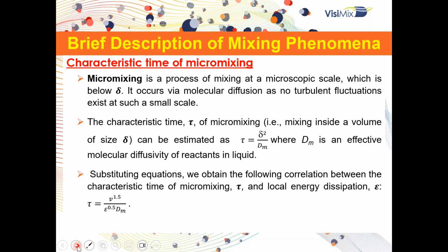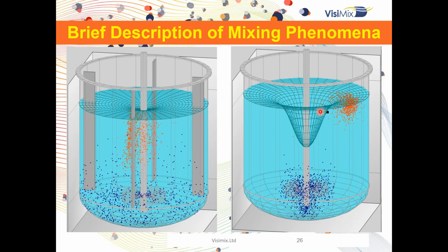I will not go deeply into it. It's very interesting to do. I include another 2 slides showing that we are able to take into consideration fluid elements in different kinds of configurations and understand why, at the same time, as you can see here, the fluid elements will be completely differently distributed for different kinds of equipment. This can give us, at the beginning, a different macro time, and after that the connection between them will be different. So this is one of the points. You see 2 equipment with the same volume but different geometries, without jacket and with jacket. You see completely different flow that will generate completely different interaction between the materials and different eddy size.